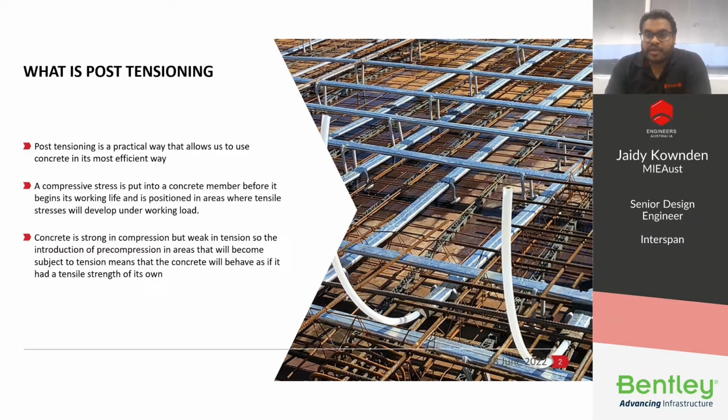As we know, concrete is strong in compression, but rather weak when it comes to resisting tension. The introduction of the pre-compression in those areas that will become subject to tension means that the concrete will behave as if it had tensile strength of its own. A post-tensioning system is an arrangement of tendons and anchorage in the slab that carry out post-tensioning.